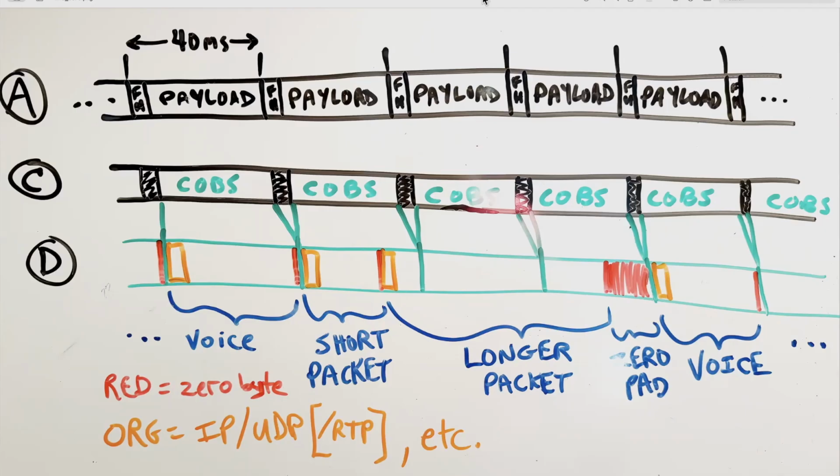Now, remember, as I mentioned before, we're encapsulating each of these frames into an Ethernet packet and sending it between our Raspberry Pi and our emulated modem, which eventually would be a Pluto SDR, but is now currently just my computer dumping out what it sees. If you imagine those as being part of a radio in a box, or a radio that you bought as one unit, that Ethernet, or whatever it ends up being, could be any kind of physical interface, is going to be very short and very reliable. It's just going to be a wire.